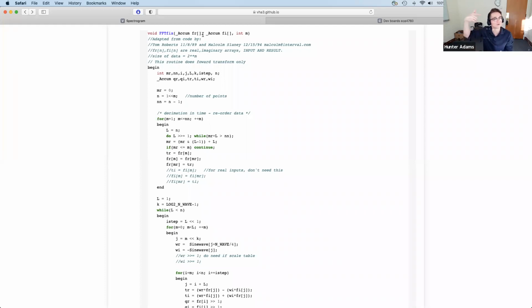So you'll interrupt 512 times, accumulate a bunch of samples. You'll window those samples, which is something I'll talk about in a moment, and store them in some array. Then you'll pass that array to this FFT function along with an array of zeros that is the same length. That array of zeros represents the imaginary part of the signal, which is zero in the case of real valued sound. The last argument to this function is the length of the array that you have passed, as a power of 2.